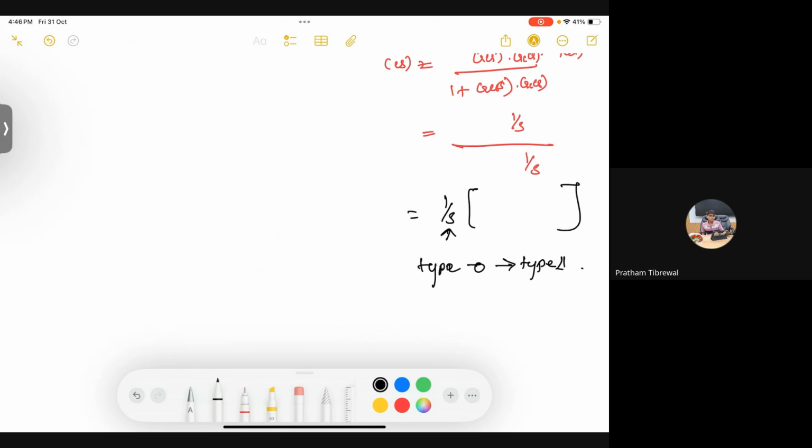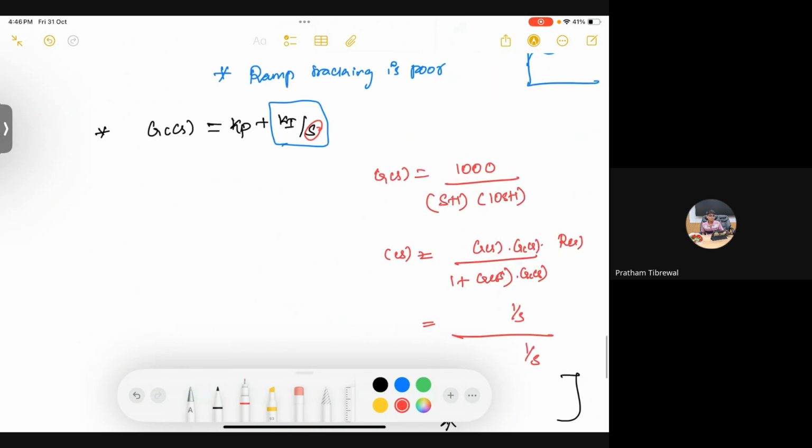For example, if you choose the same value Kp equal to 0.03, and I consider Ki nearly the same but a little lesser than Kp. It should not be more dominating because it may introduce an integral wind up action.